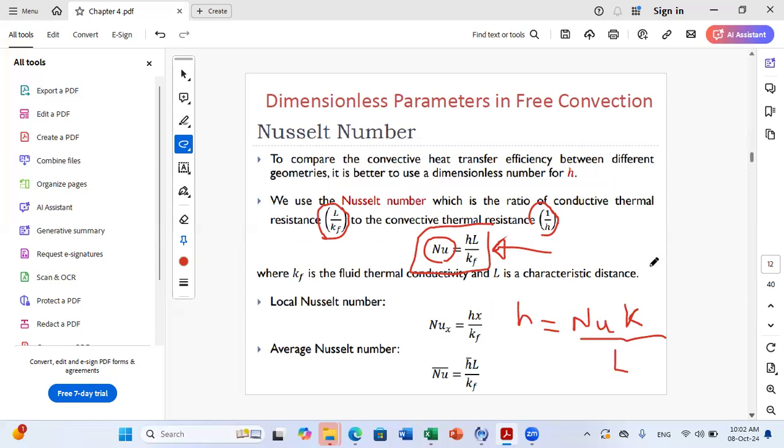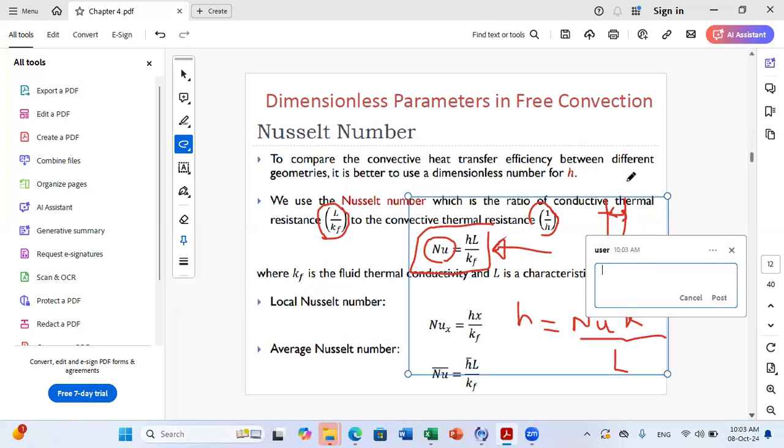If I go back with you to the previous example, you have a vertical plate with natural convection and formation of a certain boundary layer over the plate, okay? If you calculate heat transfer at this level, it will be different than heat transfer here. Why? Because the thickness of the boundary layer is changing. So you don't have the same rate everywhere, okay?